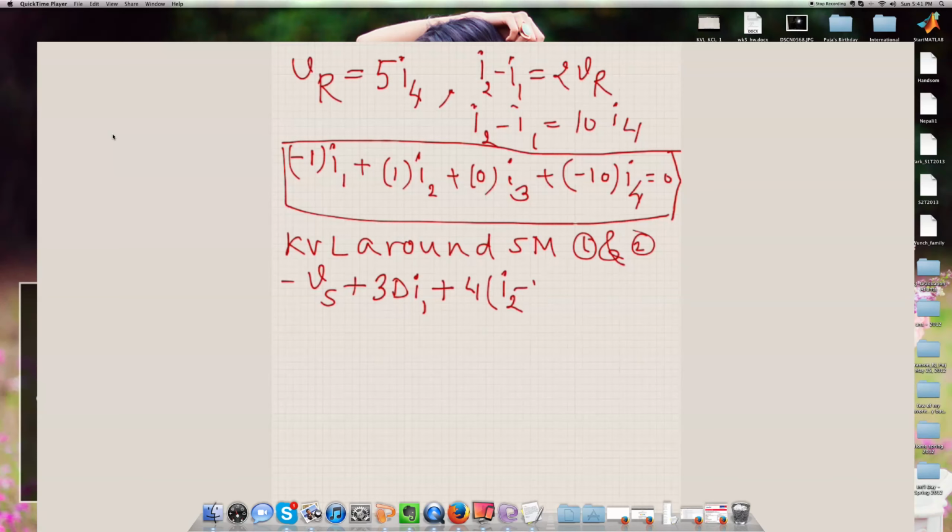And the next term is the resistance 2 ohm is there, so we're looking at the voltage across the 2 ohm, and there is again competition between I1 and I4. I1 prevails using the house rule, so I1 minus I4 equals 0.